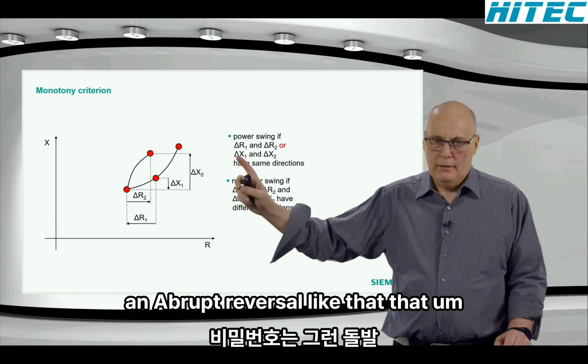It's one example. That's another example here. Here, the relay now does trip in the A phase, and you can see the dead time. The power swing continues in the remaining 2 phases, and here it's a more accurate simulation. You can see the power swing frequency is not constant. It starts off with, you can calculate the swing frequency from the dip here to the dip over there and the next dip over here. The time interval there, that's one rotation.